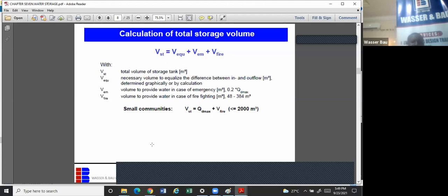So when you do that, remember, if you need 1 pump, you must provide 2. If you need 2 pumps, you must provide 3. There must be 1 off, 1 on. It is a rule. You must provide 1 extra pump, so that in case of breakdown or maintenance.